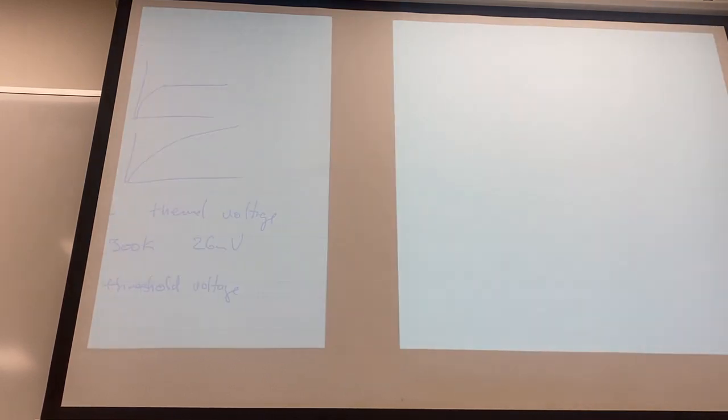Okay, so let's do the math, combine these things, and end up with a total current density expression. So J total, which I'll abbreviate as just a capital T in a second, is the sum of the drift current. Again, the drift current is just what happens when you apply voltage. So if there's no voltage applied, that's 0. Plus the diffusion current that happens just from there being too many things on one end and not enough on the other.